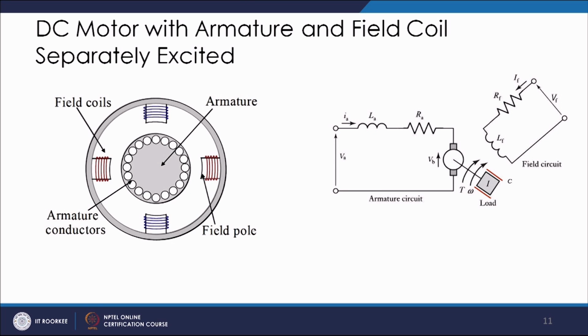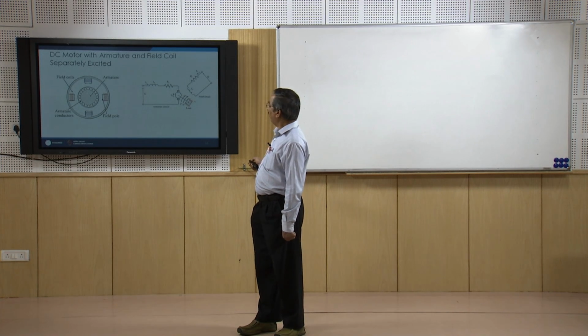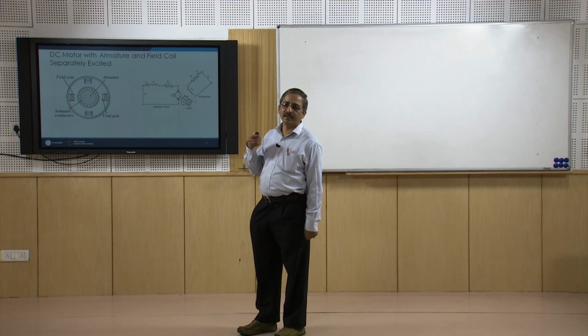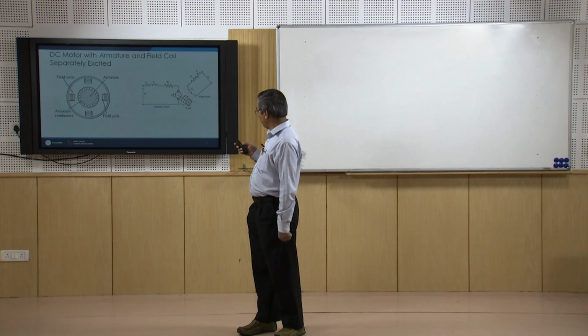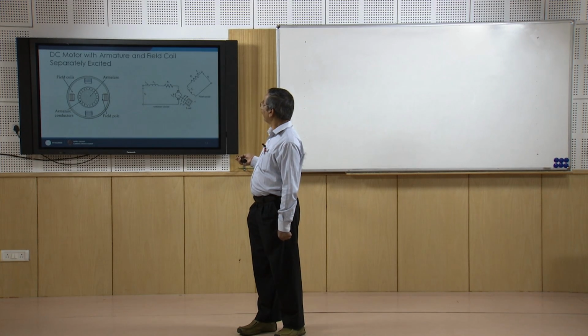So, you have a shaft here and at the end of the shaft say you have got a load, alright, and this load, that is an environment, is there. Say there is a bearing here, okay, and that bearing is generating certain bearing reaction. Say that bearing torque we can approximate by considering a damping behavior. So, we can take that as equal to some damping constant into the rotation of the shaft, okay. So, that I will be telling you.